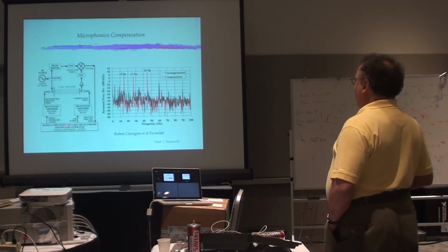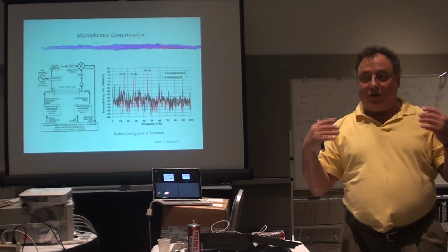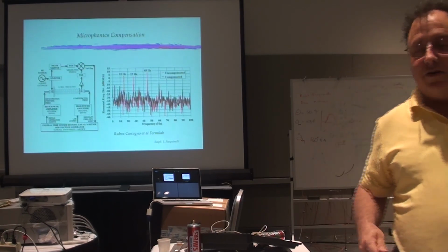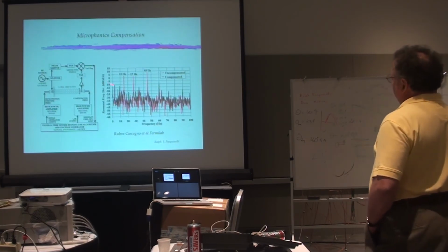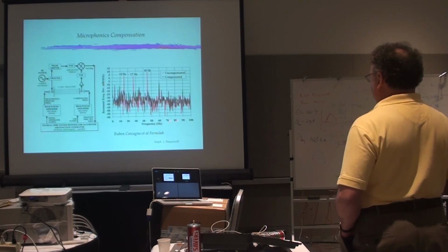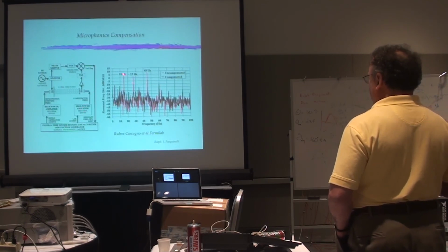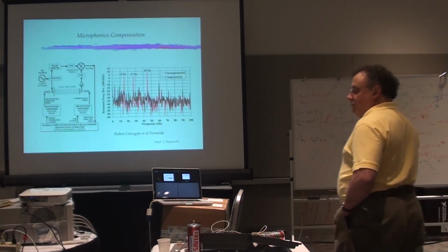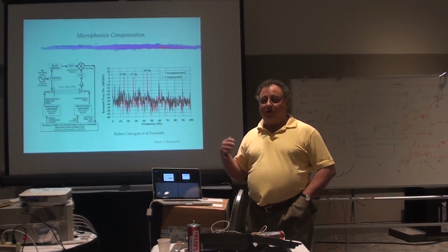The red right here is uncompensated, because I can use this piezoelectric device to anti-damp any of this microphonic noise. Here we see 15 hertz, which is a subharmonic of the line, and that could be because the pump is turning and has several modes that are line related. I don't know where 27 hertz came from. 45 hertz is yet another thing as a function of 60. This is in dB, actually dB per kilohertz, and it shows what the perturbed nasties are. With some very clever feedback we can do significant suppression, 10, 15, 20 dB of these nasty microphonic things. As you're starting to see, this has become an extremely complicated system with many things that have to work for it to work at all.